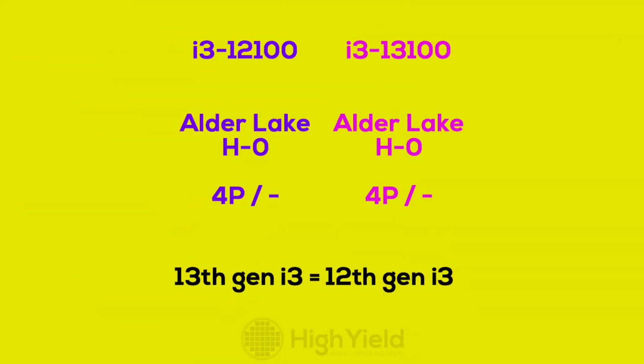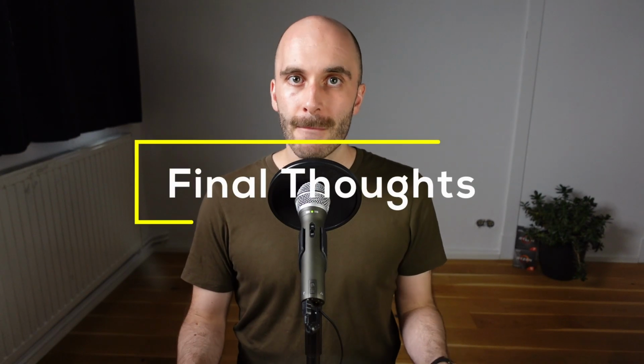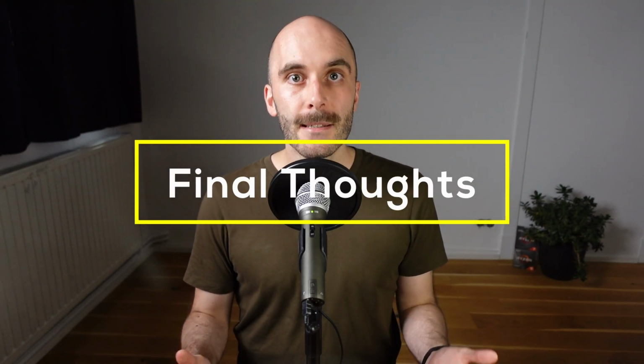The only part where I am not okay with the rebranding is the i3 13100, because it is based on the exact same H0 die as the i3 12100 and even has the same 4+0 configuration. It's literally the same CPU with a 100 MHz higher base clock dressed in a new name. That's something I cannot support. Not everything is as it seems, and not every CPU branded 13th gen is actually Raptor Lake.